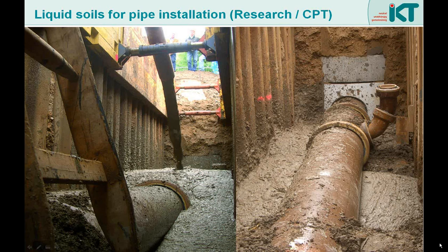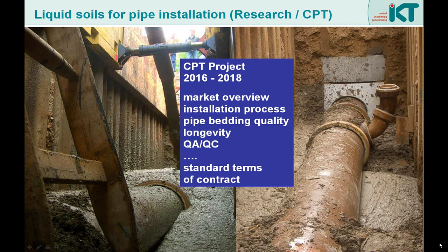Our laboratory research has shown that the bedding behavior is truly great. Stresses and strains in the pipe can be much lower than in conventional open-cut construction. The most difficult part is the installation process, and that is exactly what we are looking at in our next project. We want to take a closer look into the different products, the installation process, and the quality criteria. The goal is to develop standard terms of contract so that the material and the installation can be contracted in a reliable way.